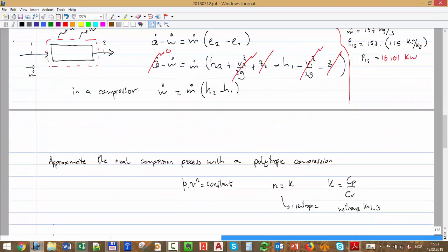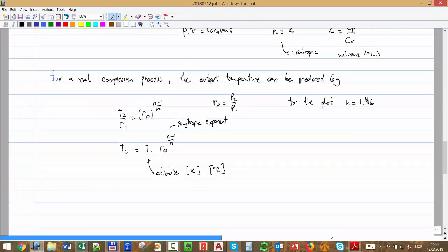So the way to do it, and I can also do some derivations, is to say that it's related to the polytropic efficiency, which is not an n, it is the Greek letter eta, and it is equal to (k minus 1) over k times n over (n minus 1). And for our particular case, that polytropic efficiency is 0.73.